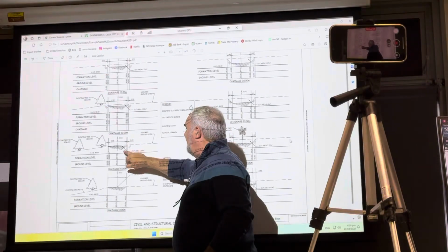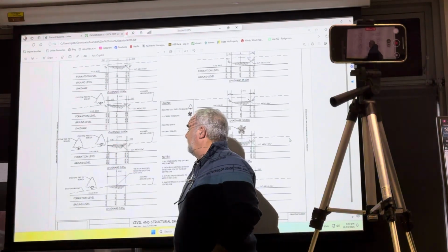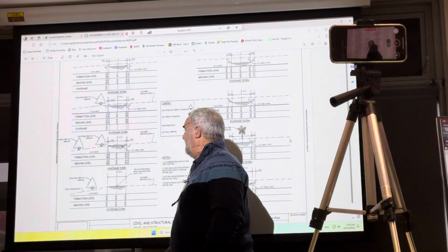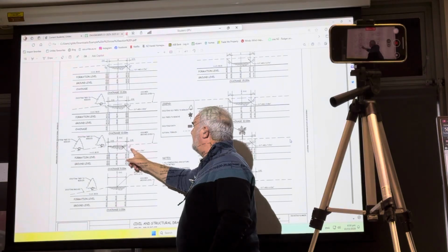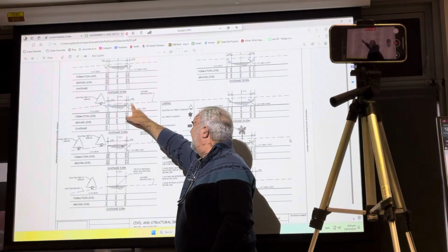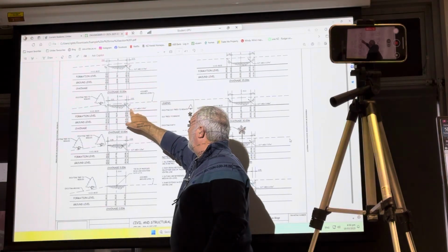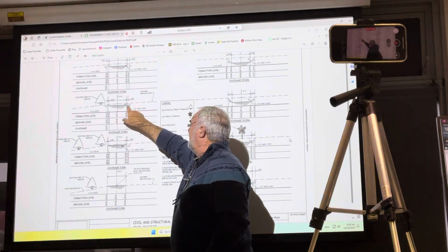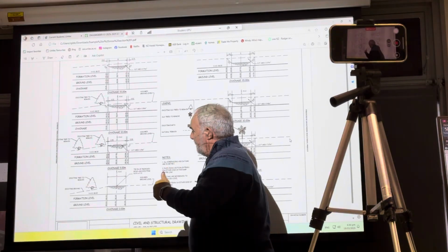That should be a solid line with the ground line underneath it. Notice it's on an angle and it looks like a basket weaving hatch. It's the proper hatch. 1-to-1 triangle, a little bit small text. Notice the size text has gone bigger for the notes. Well, it should be that size text. They've done their homework for the text and got their text perfect.